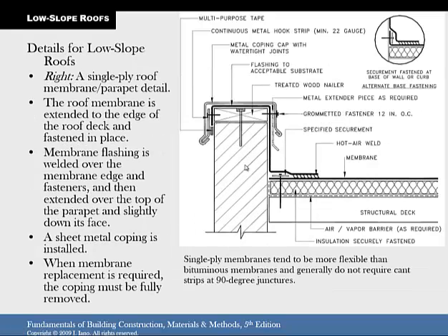And there's a side detail of a wall with a single ply membrane. Same principles. There's your membrane. Here's your, probably a membrane flashing. Then you got counter flashing and all that. So again, water would have a hard time getting up and down into that wall.